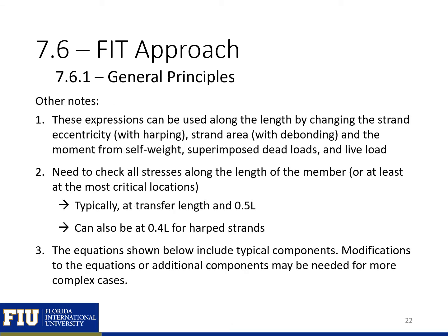I'm going to present you with a couple different equations on the next couple slides. And I just wanted to note that you can use these equations along the length by changing the strand eccentricity if you have harping, strand area if you have debonding, and also the moments will change along the length. So those will be the values that you need to update. You do need to make sure that your stresses check along the entire member length.